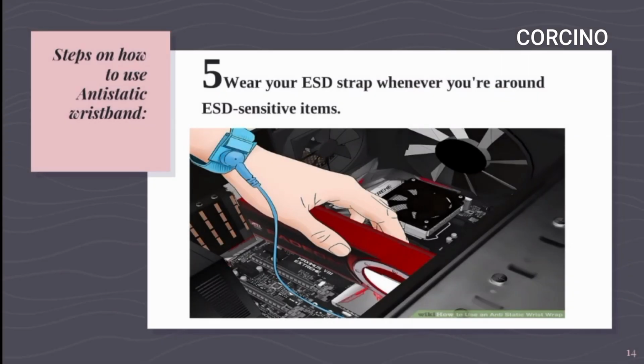Fifth is, wear your ESD strap whenever you handle ESD sensitive items. Anytime you are holding or working with computer components such as motherboards or video cards that are not installed in the computer case, keep yourself grounded. Otherwise, electrostatic discharge could damage those components.